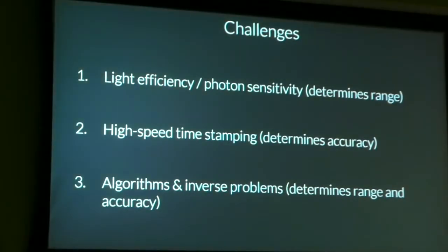So there are really three main challenges with these types of LIDAR-based 3D imaging systems. First would be light efficiency, how much signal you actually get back. Of course, you are actively illuminating something, so you have a finite number of photons that are going to travel to that point and come back. Second, how quickly you can actually timestamp or localize in time those arriving photons. And then the types of algorithms and inverse problems you can apply to improve performance, improve accuracy, and perhaps even extend the maximum range that you can see things at. So I'll spend a bit of time on each of these just to get into a bit more detail.